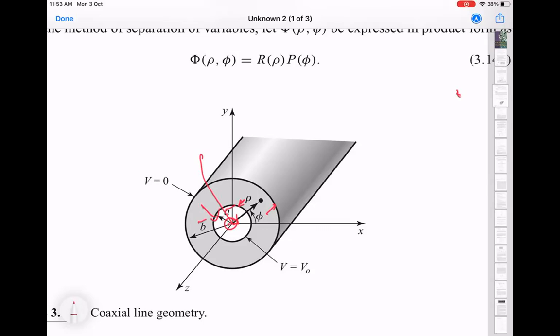And there could be two independent TEM modes, one which propagates between this surface and that surface, and another one which propagates between this surface and this surface. And if the intermediate metal, which is basically this boundary here, is thick enough, then these two don't see each other. Right? So you can have a transmission line inside a transmission line.